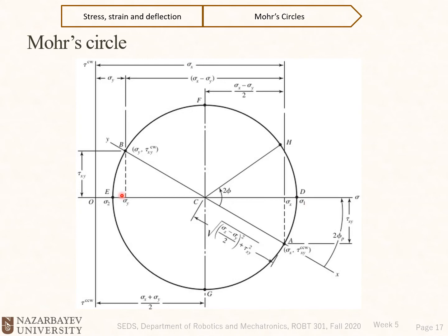Okay, so here you see the value of tau xy, and the maximum value of tau xy happens at the point F, which is the principal shear stress. Okay, so we'll go slide by slide, see how we could construct this Mohr circle and how you could work with that.